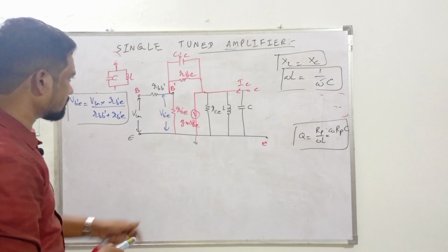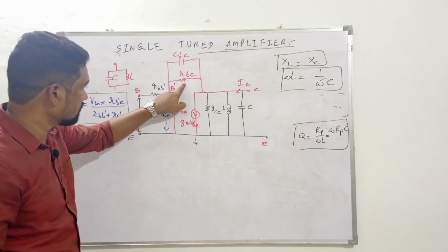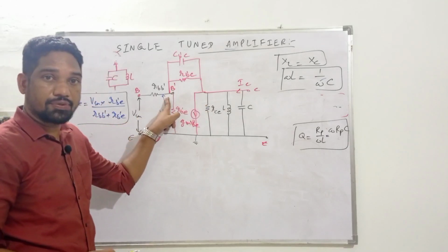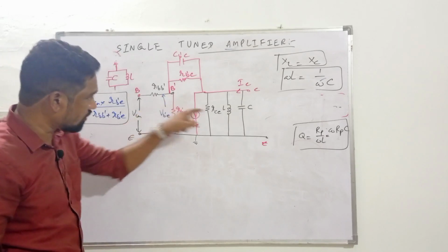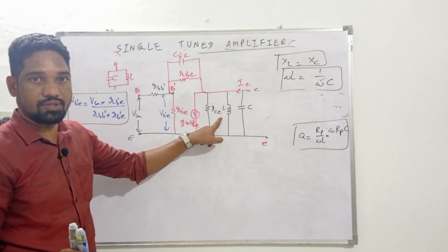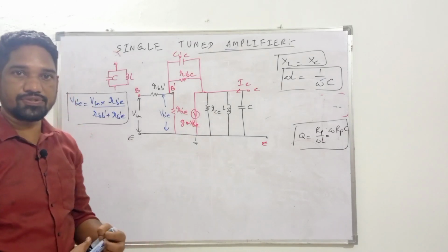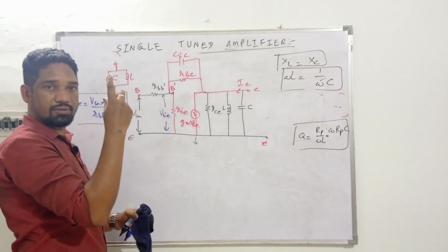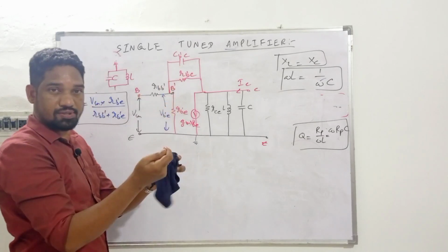So this R B dash C, which is common to the output and input, can be replaced with some other resistors in the input and output according to Miller's theorem. No proof for that one; I have already proved it making use of Miller's theorem. So take it away, plug it out, make two pieces.